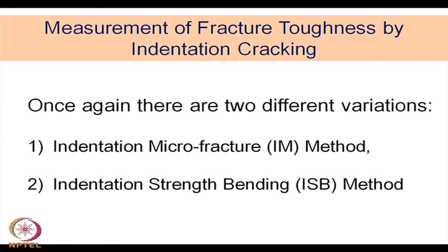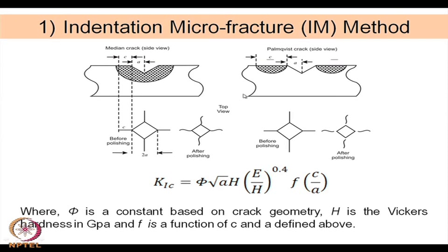So, in the first case we have just generated an indent with a diamond indenter, and then apply the load in such a way that not only does it create an indent of permanent deformation, but also creates a crack, because the load is enhanced, so that a crack is created.